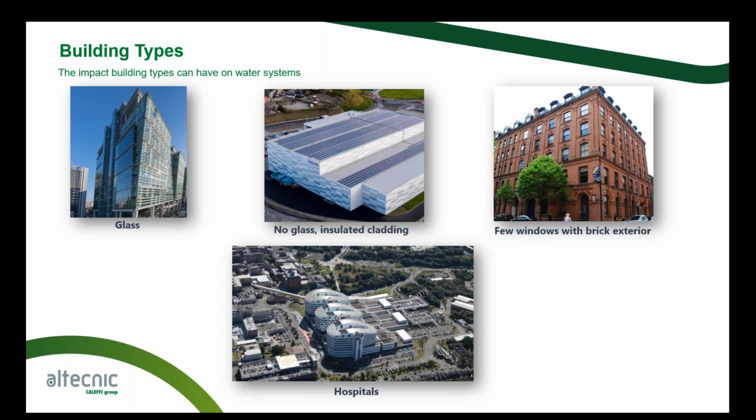The one in the centre, we look at their distribution centre again. There's probably very minimal office space, but obviously the warehouse will have various water systems running around. They tend to work in larger systems. The water tends to run across in the roof voids or the roof spaces, and that again can have an impact. Heat rises, so we know the heat is trapped up there. Again, there are long runs of pipe across there that may go around the system, so we have to think about that when we're looking at draw-off times.